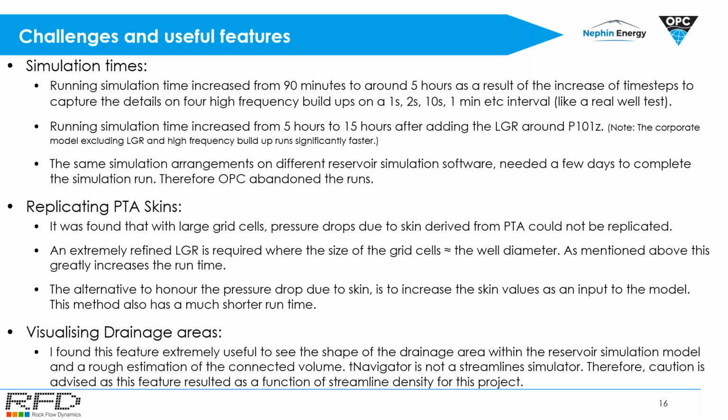Again, the simulation time went from 5 to 15 hours with the addition of the LGR. Again, it was a bit of a ridiculous LGR. That can definitely be optimized. And I tried this simulation on different reservoir simulation software, but it needed a few days to complete. Therefore, this workflow wasn't really viable with the LGRs and the very detailed time steps.